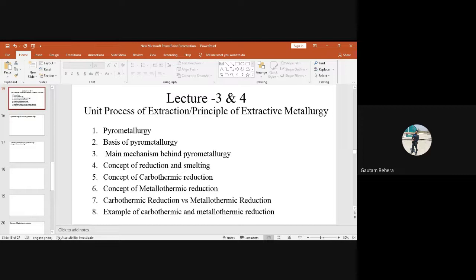So basically in pyrometallurgical processes, since we are dealing with high temperature, we can get molten metals and molten slag. It is not always true. We sometimes get solid metal also, right? But the problem is what? If we are getting solid metal by doing a pyrometallurgical process, we cannot form any kind of slag, right? So slag is the substance which contains the gangue actually, right? So the gangue cannot be removed if the metal is obtained in the form of solid. So that is one of the limitations of this pyrometallurgical process if it is done at low temperature or intermediate temperature. Fine.